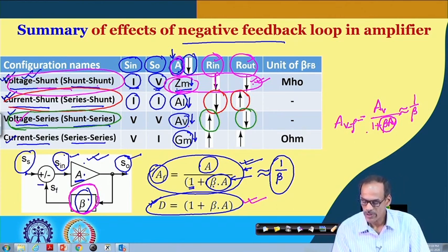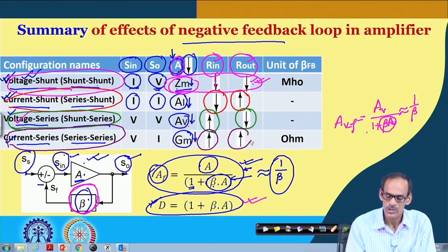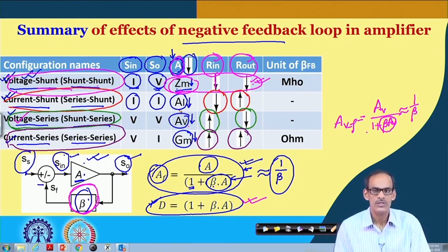And likewise, the final one, for series feedback configuration, both R in and R out are getting increased. So, this table, this summary, is very handy, and this will be helping us to decide which configuration we are looking for to achieve some requirement, namely to change the input and or output resistance, or probably either current gain, voltage gain, transimpedance or transconductance we would like to stabilize, defined by the feedback network.